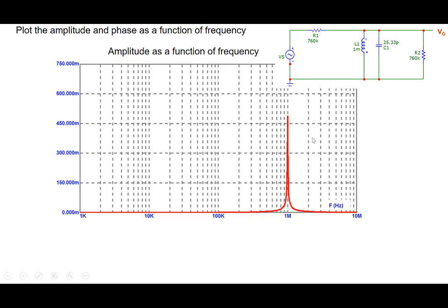And you are interested in only radio station number A with 1 megahertz. So what do you do? You pass it through a filter like this. It will pass that 1 megahertz signal, and that 600 megahertz signal will get severely attenuated. It will not pass through, right? So it's a very useful circuit, which performs the function of a highly selective, very narrow bandpass filter.